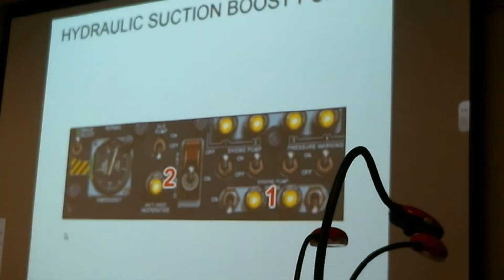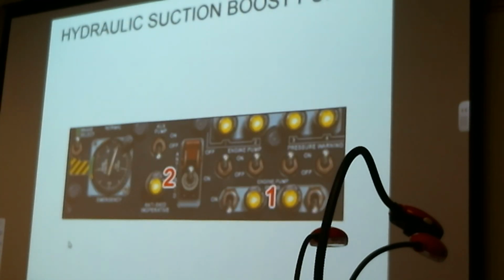On some of the Boeing aircraft as well, in addition to having an air pressurized reservoir from bleed air, they may also have a pump that has multiple stages on it. The initial stage of fluid goes through an impeller that puts an initial push on the fluid, and then after that, the fluid goes into the pump proper, and from that point on it prevents it from cavitating. So that's how they do it in some Boeing aircraft too. Okay, so that's what I can give you on reservoirs, or at least on reservoir pressurizations.